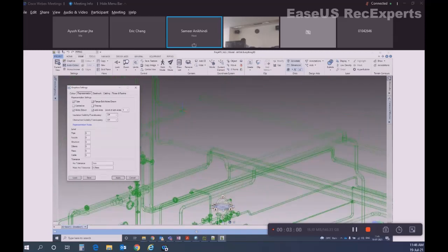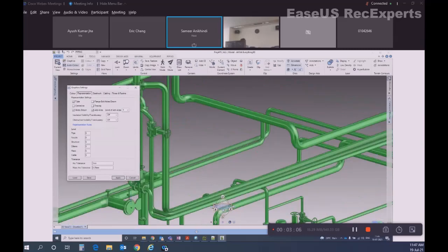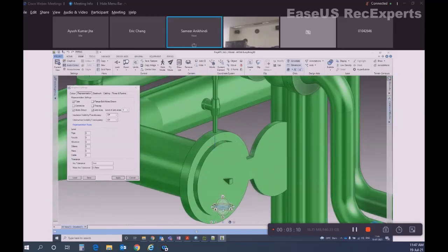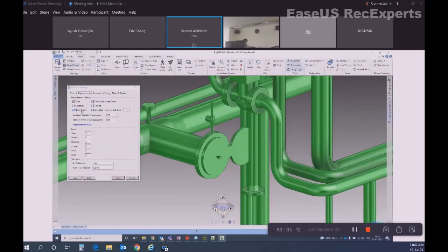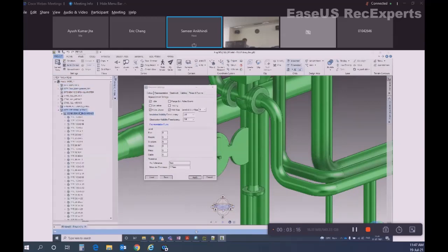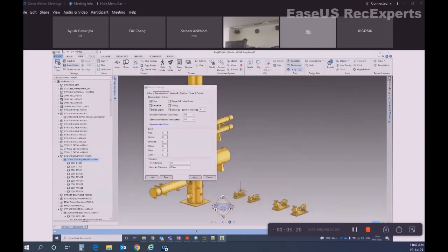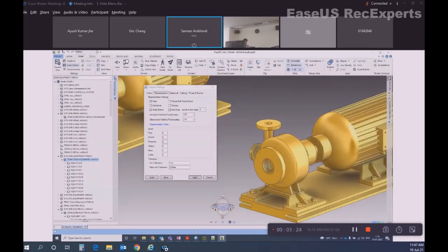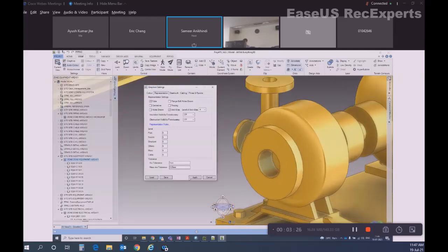Okay. So all this is for flange bolt. If you don't apply flange bolt, it will show some dotted line circles. But this hole drawn is for other things, for example, let me show you the equipments. So you can see at the nozzles, there's some hole drawn, but you can turn it off. Apply.